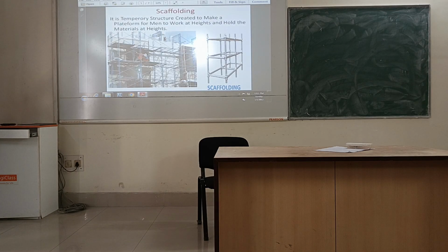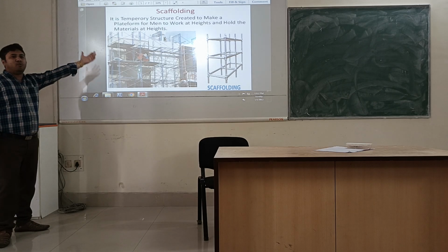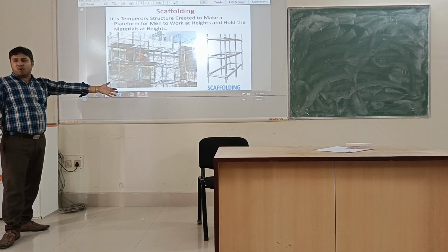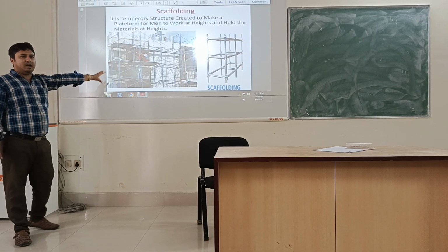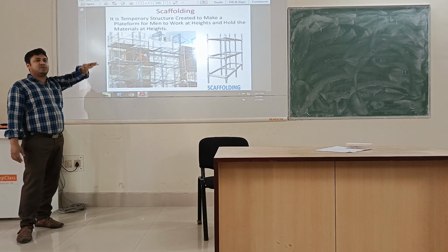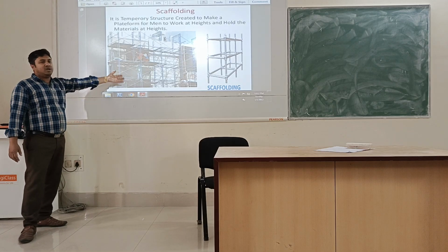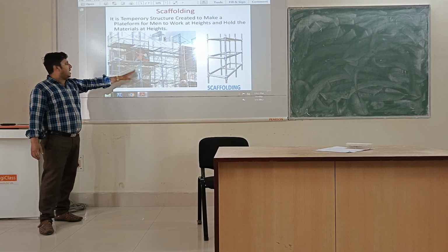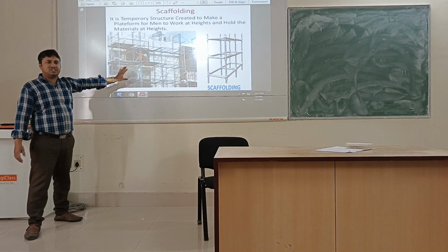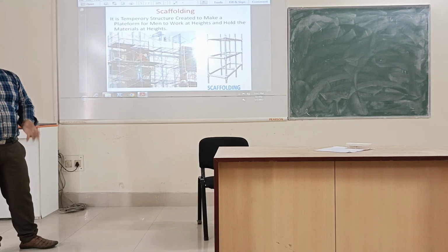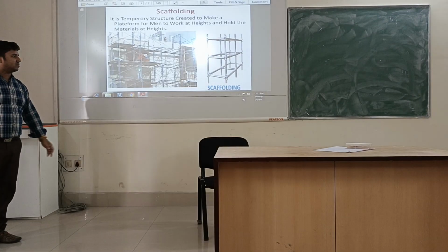Next is your scaffolding. In scaffolding, we have the workers who are performing the preparation of your finishing work in the form of plaster of a building that needs to be done in an elevated position. So if you have some elevated position, you have to put some scaffolding work, where the workers can rest and prepare the work for finishing, like plastering. So all this temporary arrangement which is made is called your scaffolding.